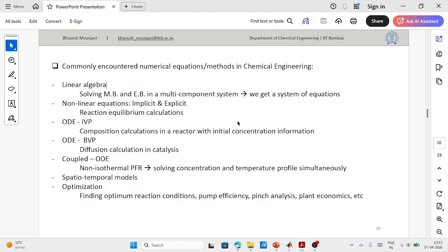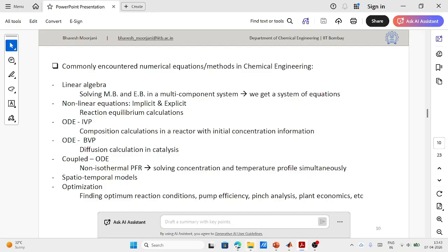So what are some examples? The distillation column is the best example. You have an overall mass balance between components going in and out. Then you have the individual component mass balance. If you want to go into further detail, in a distillation column you have multiple trays, so you can do a mass balance at each tray stage also. In the same way, you can consider energy balance examples.